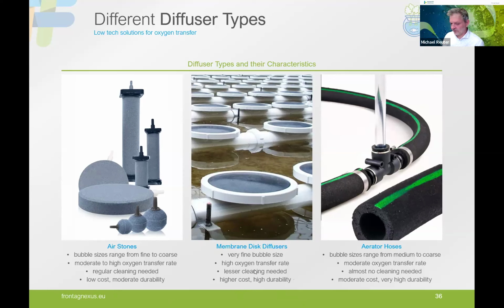And that's what I also noted here. The oxygen transfer rates are probably moderate for air stones, much better for membrane disc diffusers, and also moderate only for aerator hoses. But also the costs, so the investments, are different. Air stones are really low-cost devices, while membrane disc diffusers are more on the higher cost side. But they also have better durability than, for example, air stones. We would have to exchange the air stones more often than the membrane diffusers.